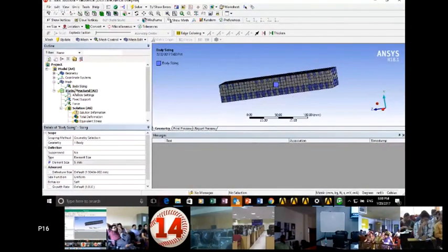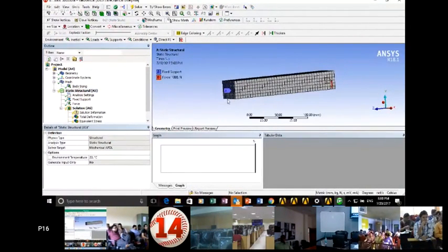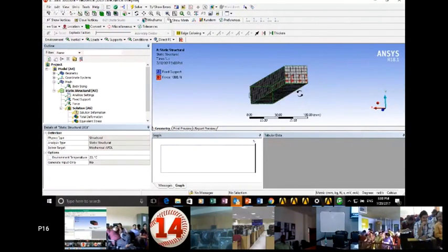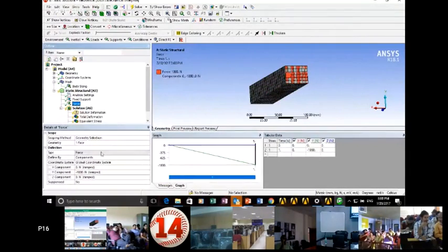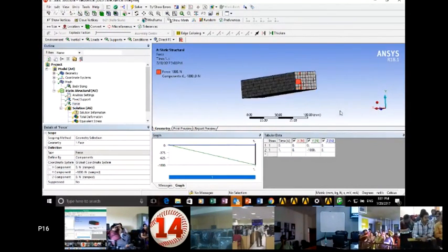Now I'll assign boundary conditions to that model. I have assigned a fixed support at one end and a point force at the other end. Now the value of force I have parameterized. How to parameterize a particular value? You can see I have entered a force in the negative y direction. In order to parameterize a particular value, I'll simply check the checkbox next to that value. So whenever you check a particular checkbox, it will get parameterized.